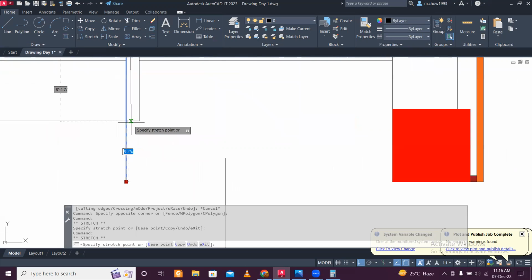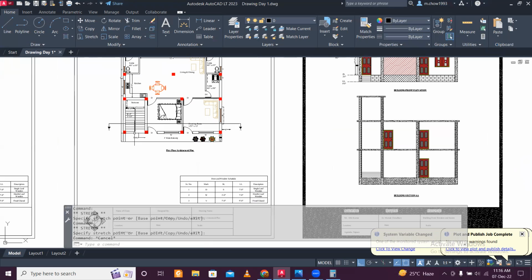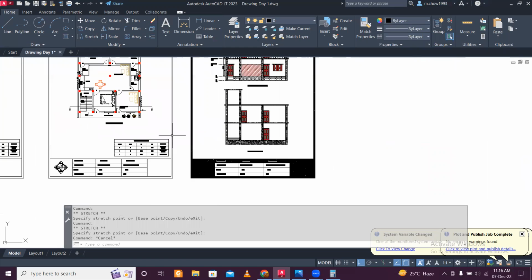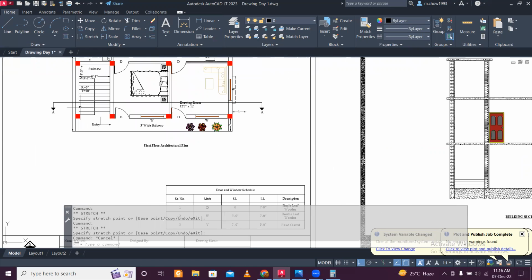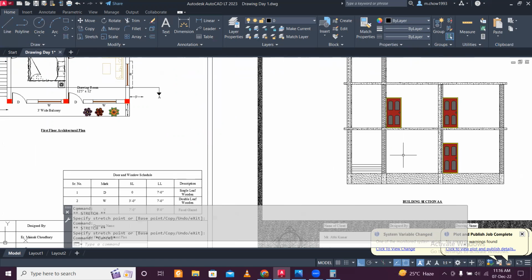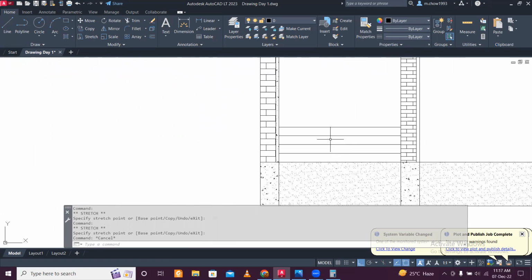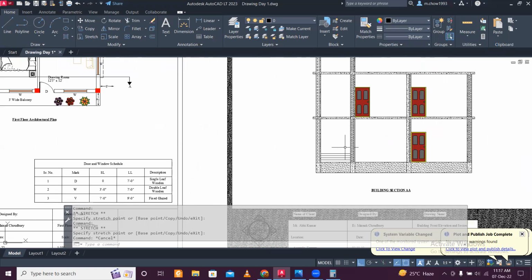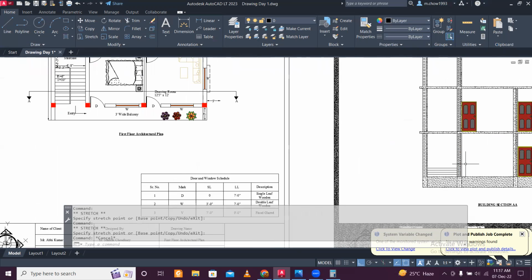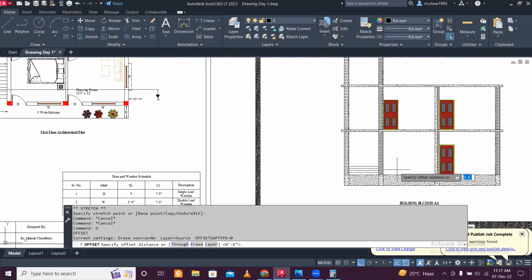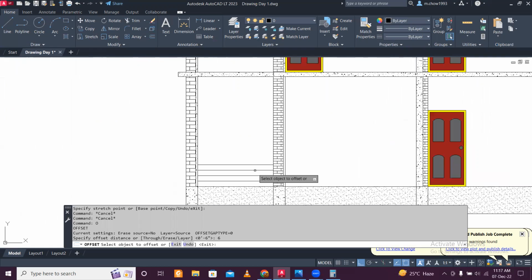Okay. So this is 11 and 10 steps in the risers each. So here, obviously, when you are starting from this, we have this one riser, 2, 3, and 4. And up to the landing, we'll have 11 exactly. So 6 inch we're taking.